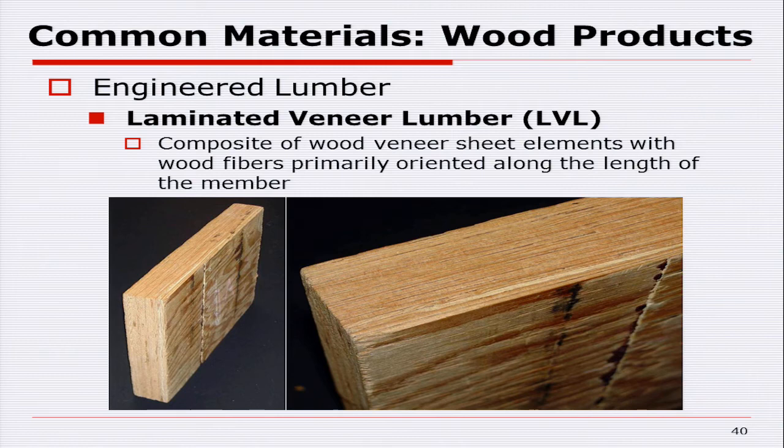The downside of this, you understand. You know what the advantage of going crossways was, is that you had strength in both directions. And also when you put a fastener into a piece of plywood where you've laid one layer this way, one layer that way, you don't get splits. This stuff, believe you me, you drive a fastener into it, it will split just like a piece of lumber will, because all the grains run in the same direction.